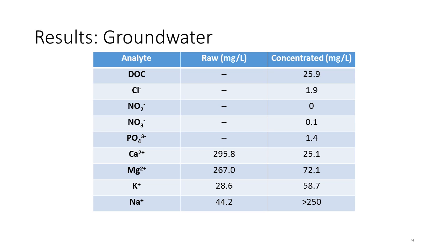I assume the RO is a single pass through, and what's the recovery from a permeate flow versus feed flow perspective? Single element, single pass? Well, I guess it's not a single pass in that we're basically refiltering the same water that we're concentrating. But from a process perspective, the flow's in, the flow's out. It's not going to another, different membrane. So yes, it's a single pass.